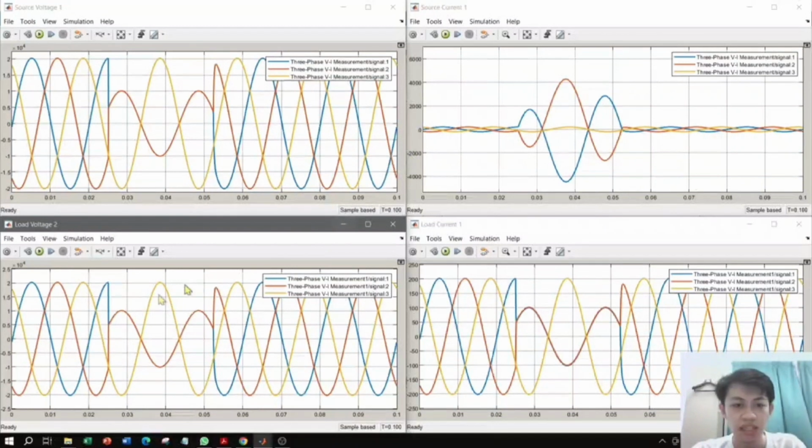And as we can see here, there will also be voltage and current in the load because the fault current is cancelled out by each other. So the breaker will not totally shut down the connection to the load, but the voltage and the current in the load are a little bit smaller compared to the normal current and voltage in phase C.